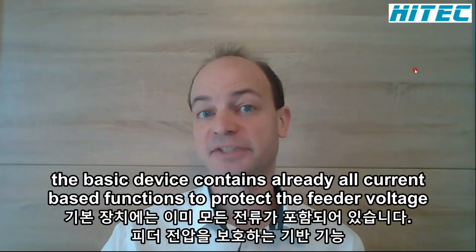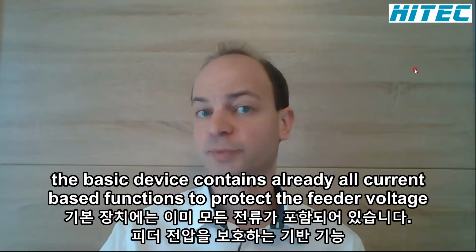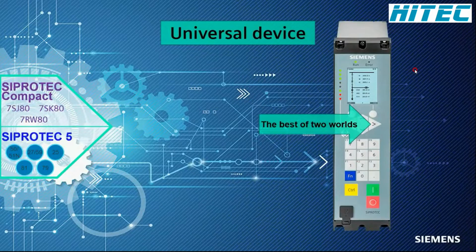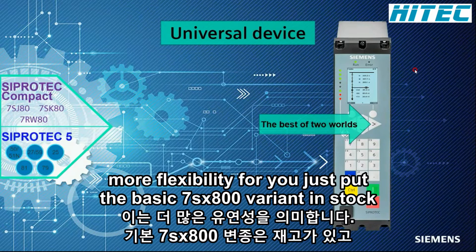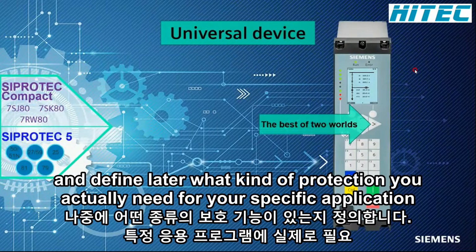The basic device contains already all current-based functions to protect a feeder. Voltage-based functions or motor protection functions can easily be added anytime using function points. With our universal power supply, the relay can be used anywhere, regardless of whether the auxiliary voltage is 24 volts or 250 volts. This means more flexibility for you. Just put the basic 7SX800 variant in stock and define later what kind of protection you actually need for your specific application.